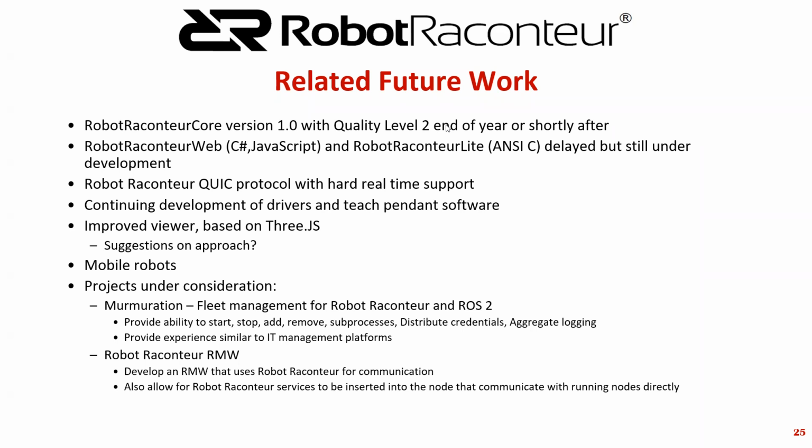The problem we're having with the native onboard commands is that the update rate is really unpredictable. Sending a command to a robot can have a delay between 10 or 100 milliseconds. So streaming commands isn't always the best option. What we are doing now, I was just working on it yesterday, is you have the ability to send an entire sequence of commands to the robot in a file. And you also have a preempt option.